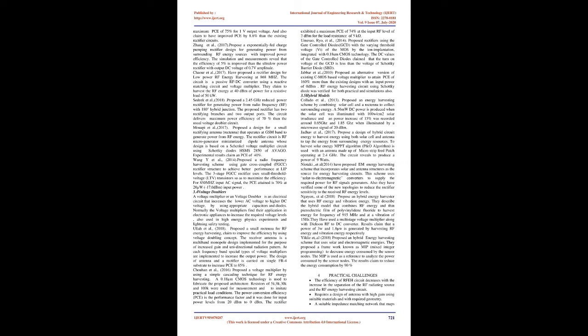Saini et al., 2016, proposed a power management scheme for RF energy harvesting. Design features reveal that the maximum power efficiency is gained for a specific range of load resistance. So the input resistance of the DC-DC booster is the same as the load resistance in order to get maximum power conversion. The circuit is fabricated using 180 nm mixed mode CMOS technology.